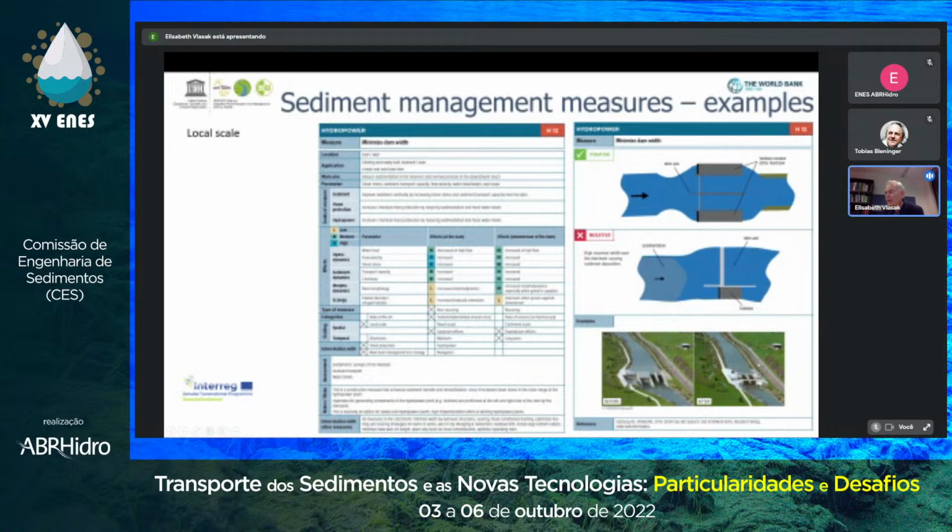So the width, the transport capacity, is a big topic. In almost all hydropower plants, this is much larger than the river width. We did some scale models, and I could send you a paper if you're interested. The width, of course, determines the sedimentation, so we also don't want this big increase. This is a planning point.